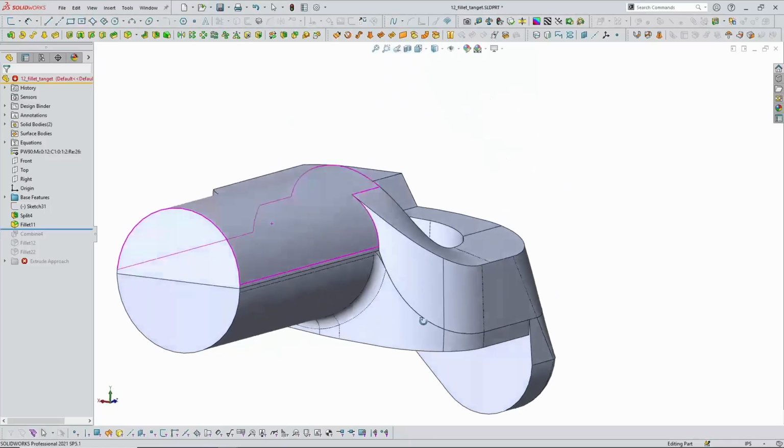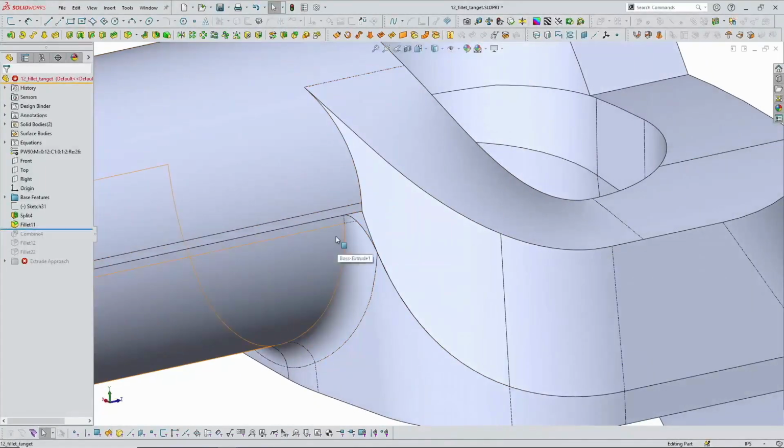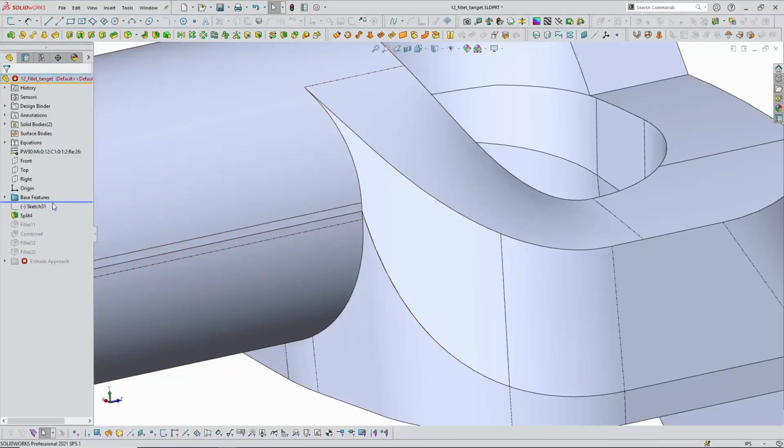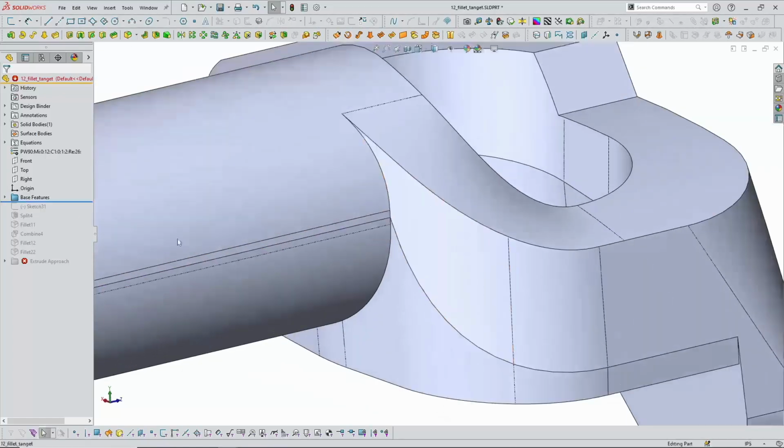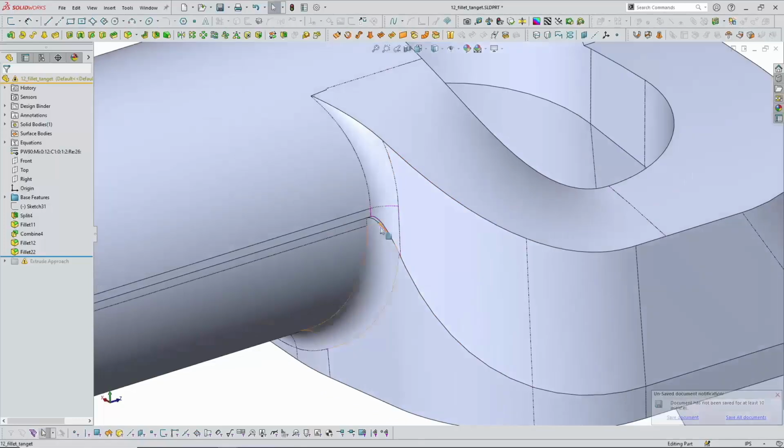So once I split this at the parting line, when I add my fillet here, it's a lot smoother than it was before. And that was because these two different angles coming together introduced a little bit of waviness as it came to this intersection. So depending on the fidelity of the cast part or molded part that you're working on, this may be totally acceptable, and that this being the mismatch at the parting line.